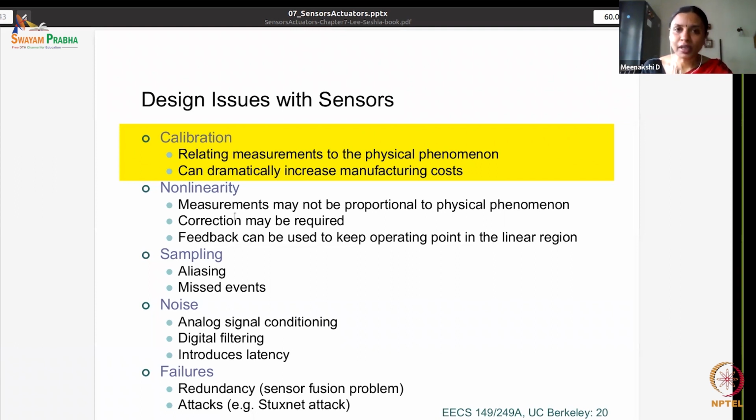Sensors could also fail because they are, after all, hardware devices. So, because a sensor can fail, we usually keep redundant copies of the sensors. If you keep two or three copies of the same sensor that is meant to read the same kind of data from the same physical phenomenon, how do you decide which sensor's data to use? There are sensor voter algorithms or sensor fusion algorithms that help you decide which sensor data to use.